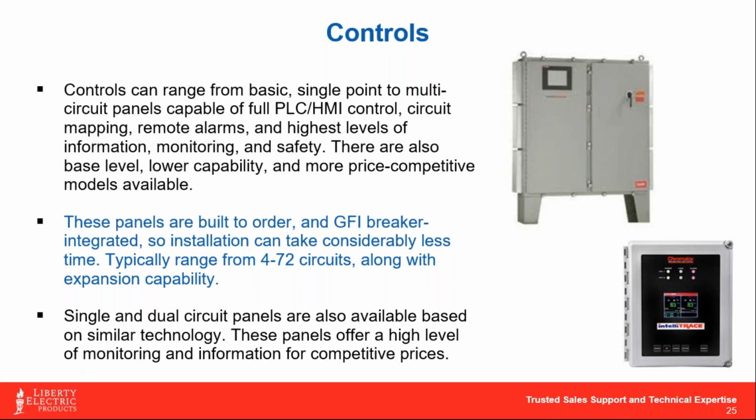On the high end of things, we've got fully integrated heat trace panels that are breaker loaded. You can almost look at them like they're their own separate load banks. The nice benefit is that this is a fully integrated panel that's going to have breakers in it, contactors in it, GFI protection in it, and an HMI touchscreen, so you can access information that goes far and away beyond what standard mechanical based controls are going to give you. You can put alarm options into these things. You can tie circuits together.